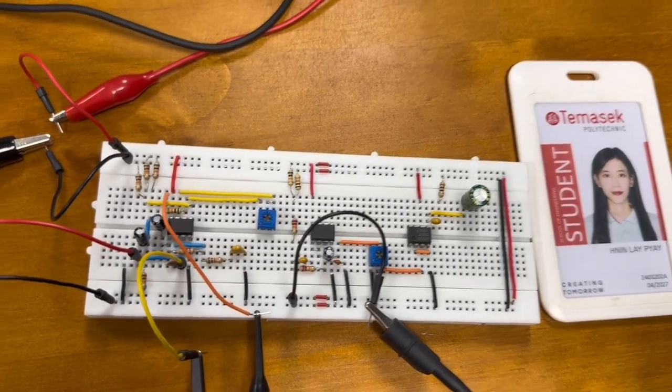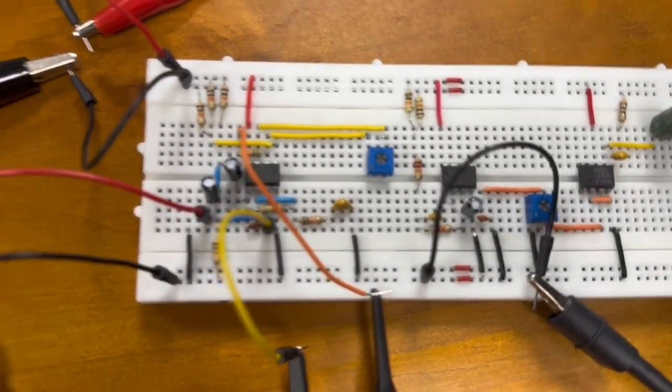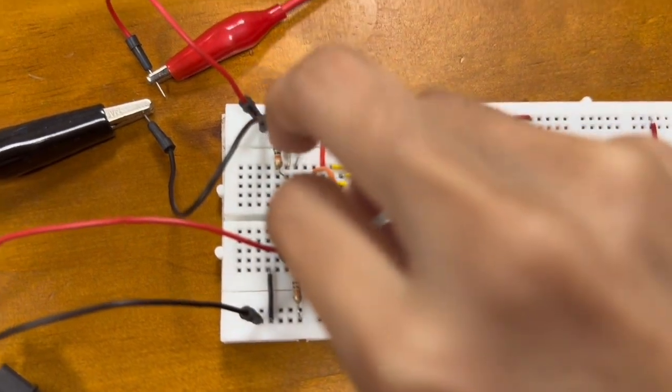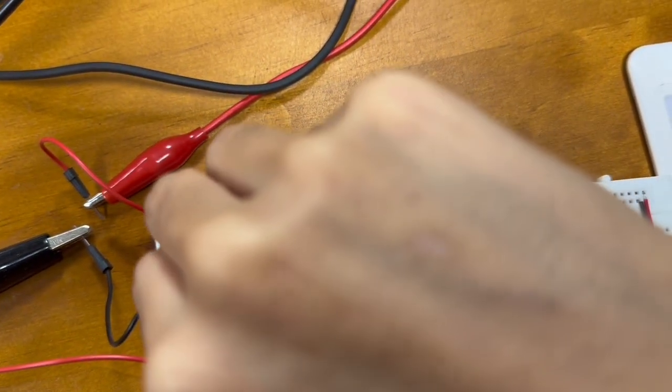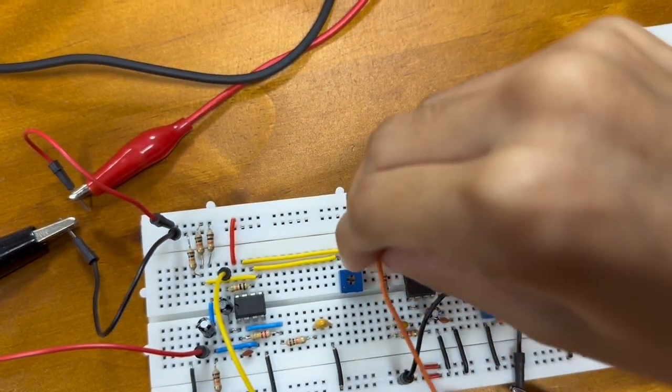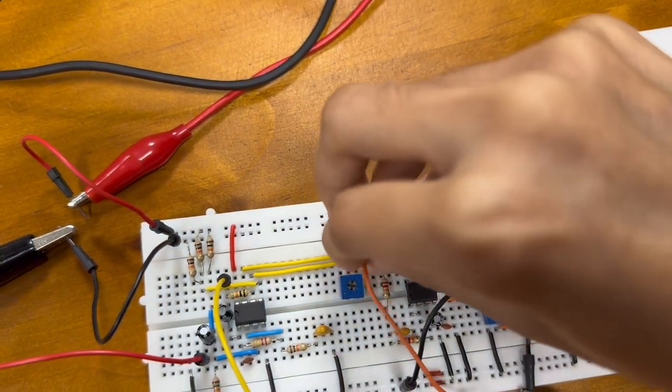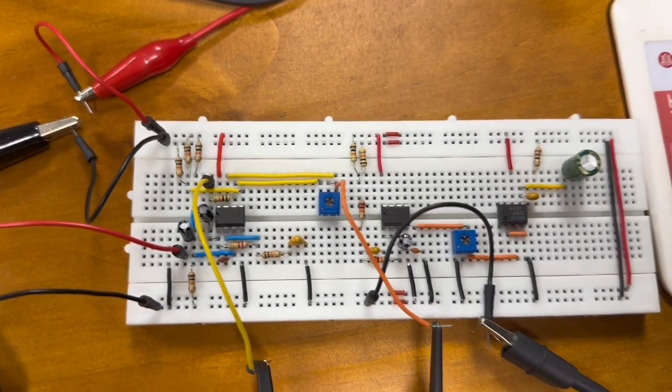To set up stage 2, we will put the output of TP2 at channel 1, and the frequency as well as the power supply are left untouched. We will place the channel 2 probe of the oscilloscope at TP3, then we can get an output voltage of nearly 6 volt.